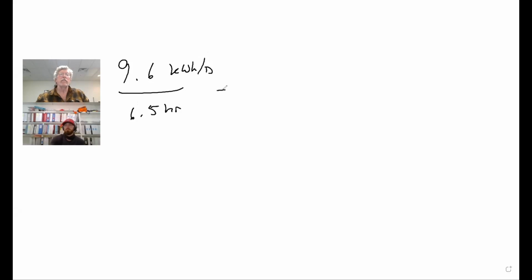All right, so we said her total system is 9.6 kilowatt hours, and I think that was per day. So we divide that by 6.54 hours per day. Those cancel out, and we get, I'm hitting my calculator here, 9,600 divided by 6.54, 1,477.